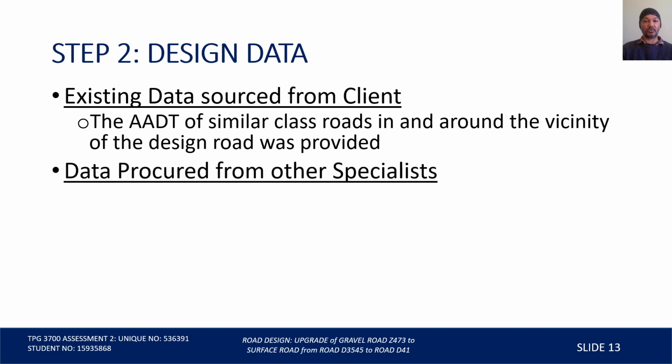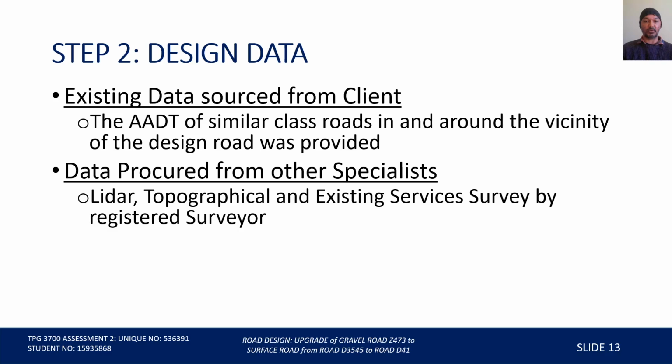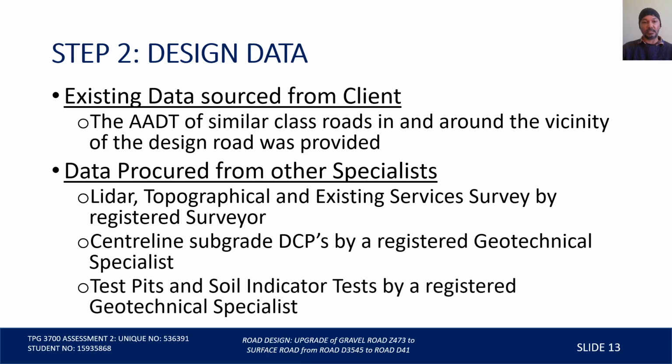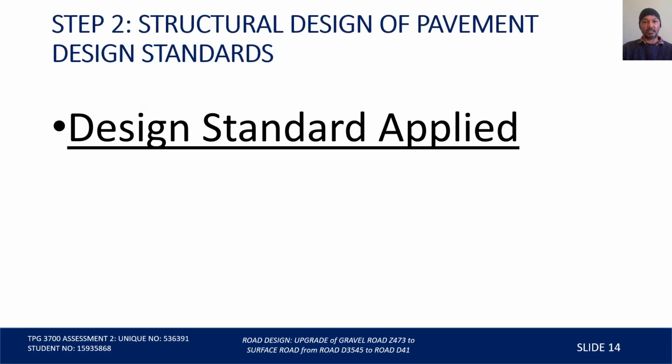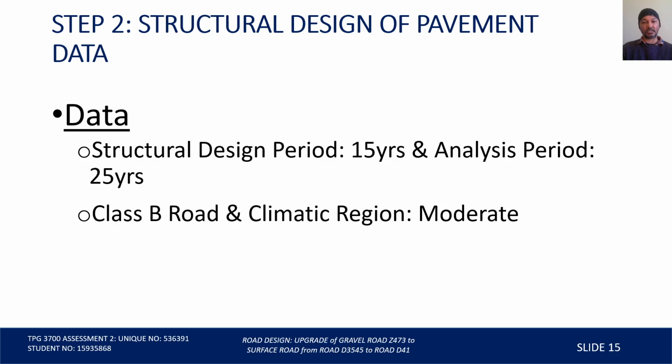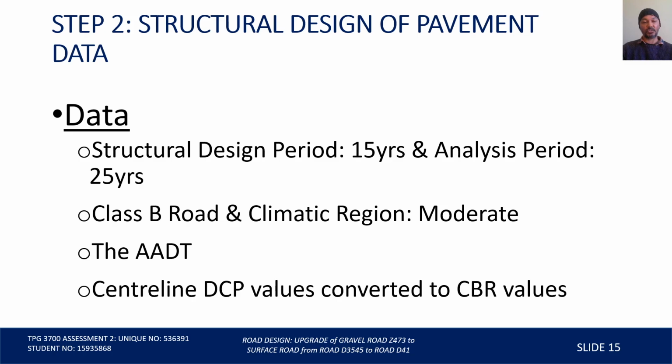similar roads, data procured from other specialists in the form of LiDAR topographical and existing services surveyed by a registered surveyor. Centerline DCP subgrade tests by registered geotechnical specialists, and then test pits and so on, indicated tests by registered geotechnical specialist. Design standard for the structural design I used was TRH4. These are the data that I used: the structural design period, the climatic region, and the average daily traffic. And the centerline DCPs were converted to equivalent CBR values.